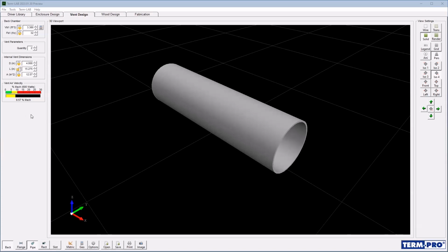For instance, if the system is mounted behind a seat, the upholstery in the seat is going to attenuate the high frequency harmonic components that are audible from port chuffing. Or if the system is playing at full power, it may be so loud that your ears are distorting. You may not be able to hear the port turbulence just because the system is playing so loud. In this case, let's just say this is good. We're going to accept this.